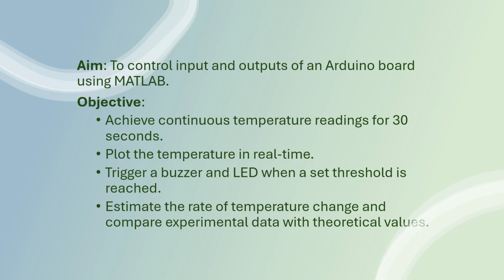Our main goal in this lab was to control the input and output of an Arduino board using MATLAB. Specifically, we wanted to achieve continuous temperature readings for a minimum of 30 seconds, plot the temperature in real time, and trigger the buzzer and LED when the temperature exceeded a set threshold. Additionally, we wanted to estimate the rate of temperature change and compare the experimental results with theoretical values.